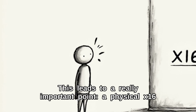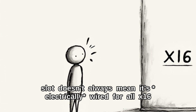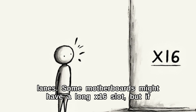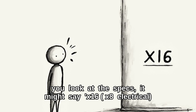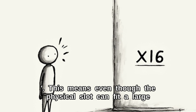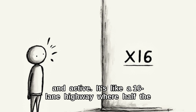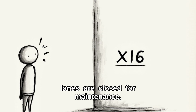This leads to a really important point. A physical X16 slot does not always mean it is electrically wired for all X16 lanes. Some motherboards might have a long X16 slot, but if you look at the specs, it might say X16, X8 electrical. This means even though the physical slot can fit a large X16 card, only 8 of those lanes are actually connected and active. It is like a 16-lane highway where half the lanes are closed for maintenance.